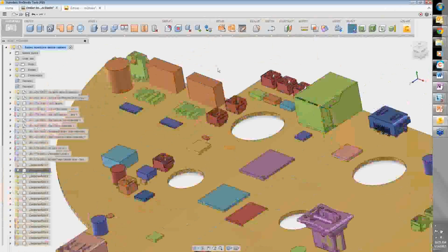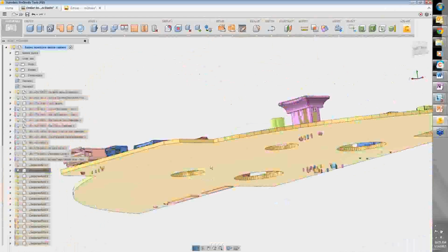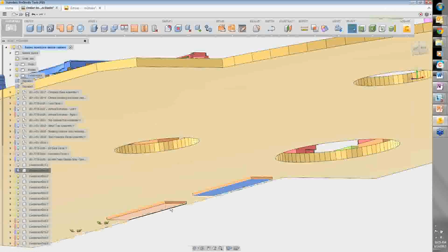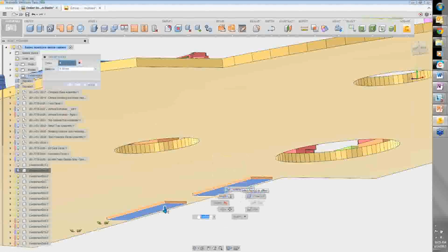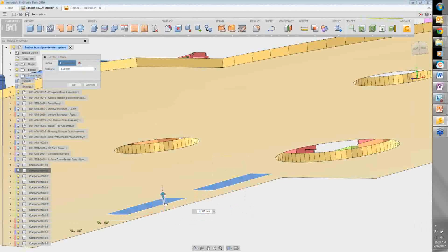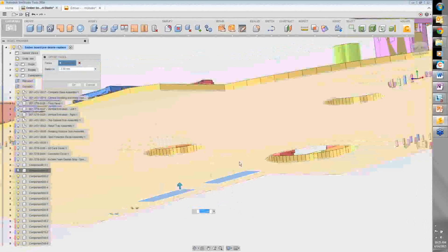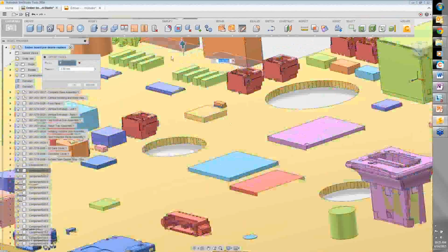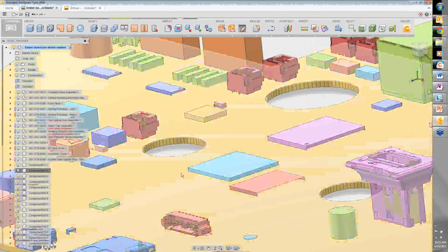Now, that box protrudes all the way through because the pins came all the way through. So I didn't adjust this bottom portion, but this is kind of cool. I'm going to grab these two edges, right-click, Push/Pull. I grab my handle, and I can move it up and try to position it right. But if I just click on the surface, it'll snap to it. Now I have it perfectly positioned.